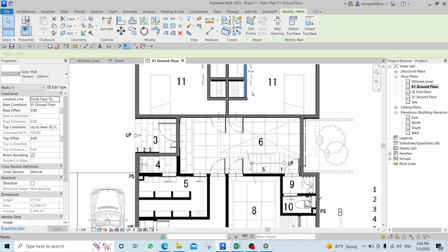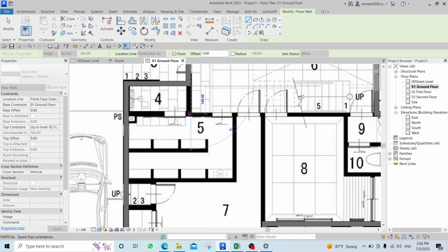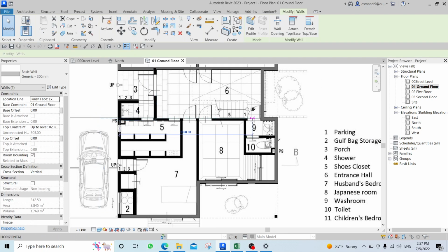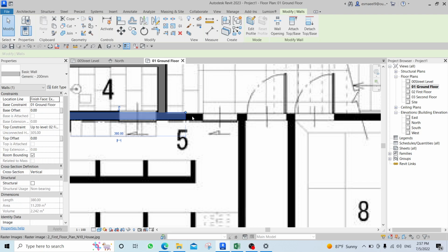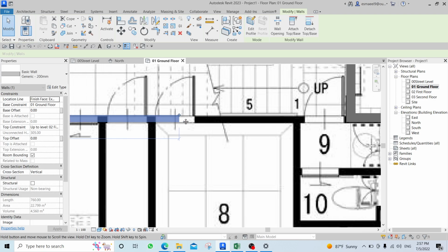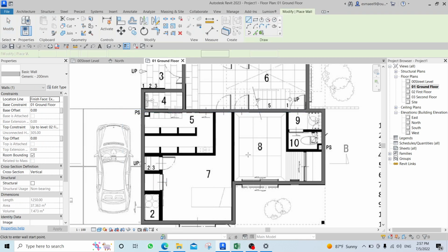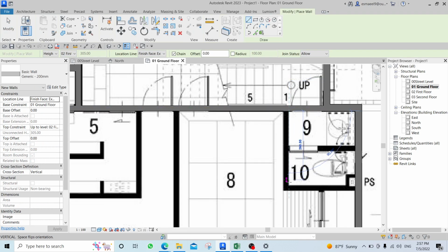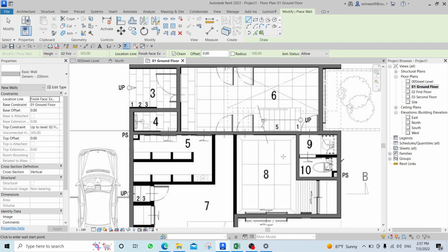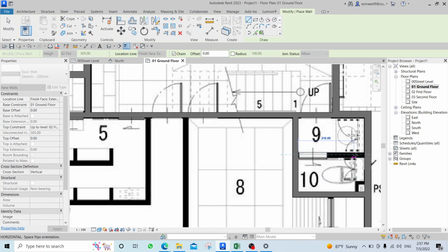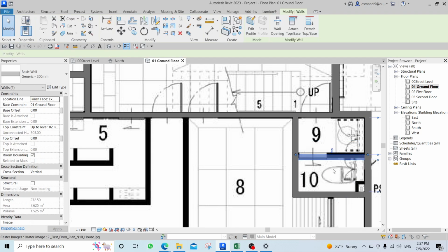Click on this wall, CS, use it, face exterior is selected, put it into here, like this. Bring this wall and move it. As you can see, I'm just selecting something and there is a little point in here. Drag, I'm just dragging it in order to make it a bit longer. CS again for create similar. Select it, draw something like this, draw something like this. Okay, like that. I'm just drawing now. Little walls.